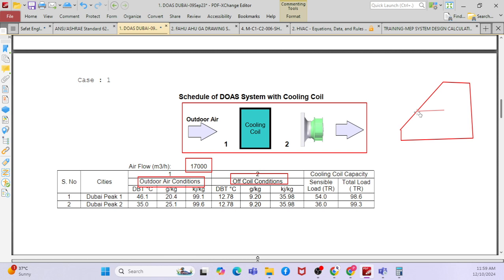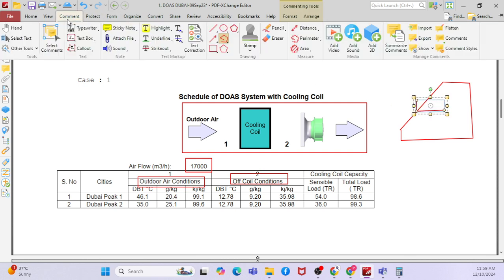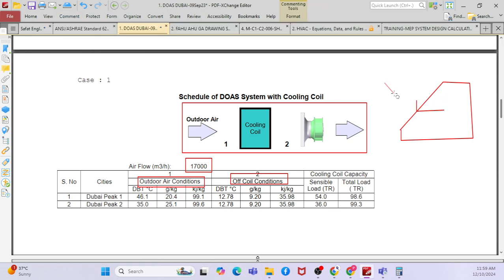But when you go to comfort cooling, you have both latent and sensible load, right? Now you know the value called the sensible heat factor is nothing but sensible load divided by total load. If you go to the psychrometric chart, there will be a semicircle.